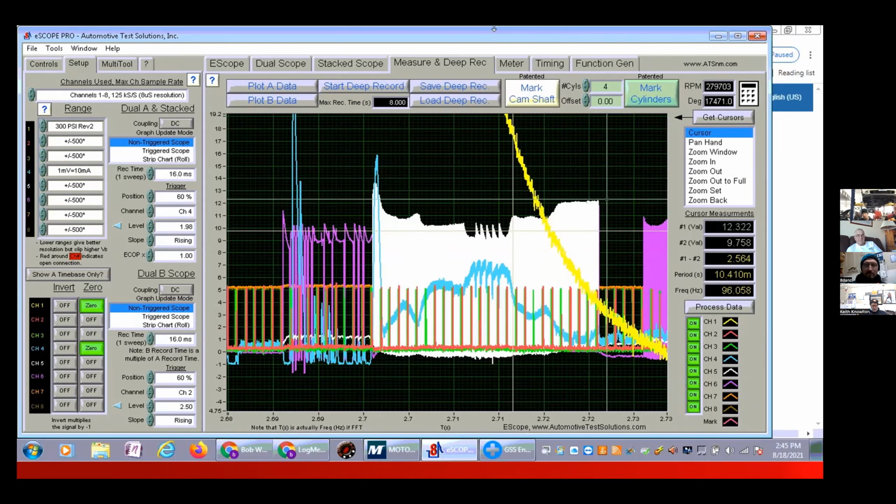And believe me, I almost melted out of my chair, guys, when I opened up that sheet and looked at what the default strategy was for the chip in an overcurrent condition. 5 reset attempts in 500 milliseconds, and then it shuts off and it defaults, and it won't let it start again until it's repaired or cleared. Okay. Now, if that does not connect the dots to all that ethereal information in that box that the OEM never gives us to make these diagnostic calls, I don't know what does.